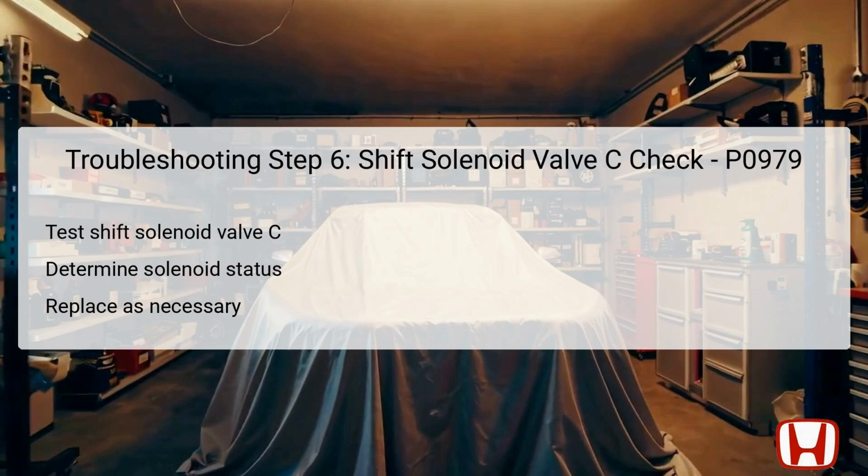In contrast, if the solenoid fails the test, it will need to be replaced outright. This decision will help ensure reliability and performance in the vehicle's transmission system. Regardless of whether you're replacing the harness or the solenoid, remember to conduct repair verification following any corrective action taken, as this is crucial to confirm that the original fault has been resolved.